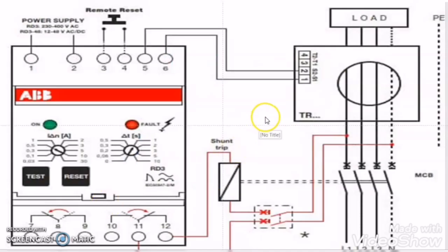So now let us take two examples and then we will analyze this CBCT response. Suppose in the first condition, 50 ampere of current is flowing from the source to the load through the CBCT and the condition is normal, there is no earth leakage fault. Then the phasor sum of all the currents at every instant is equal to 0. So the CBCT will not get any induced EMF as the resultant current passing through the CBCT is 0. Now let us take another case, where this time 1000 ampere of current is flowing through each phase. In the first case there was 50 ampere of current. Now in the second case 1000 ampere of current is flowing through the CBCT and it is a normal condition. So again the resultant current in the CBCT is 0, as the phasor sum of the currents at any instant of time is always 0 in the normal condition. So again the CBCT will not get activated as the resultant current is 0 and this load will function.